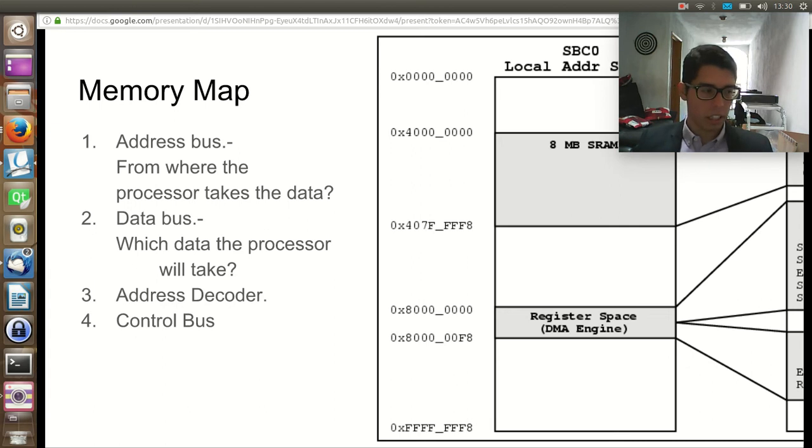All of this between the address bus and the data bus is handled by the address decoder. An address decoder interprets the upper bits of the address bus and selects the appropriate memory or peripheral chip. Then the data is transferred over the data bus. It's sending a message, returning the data.